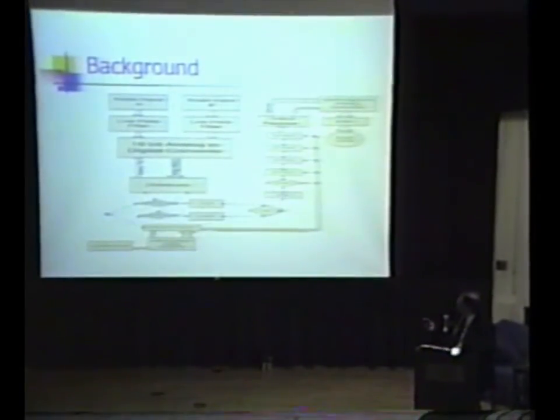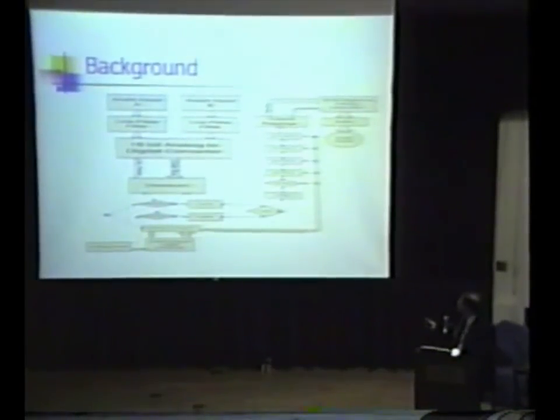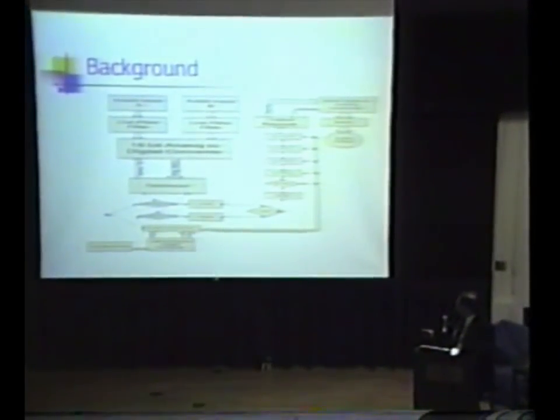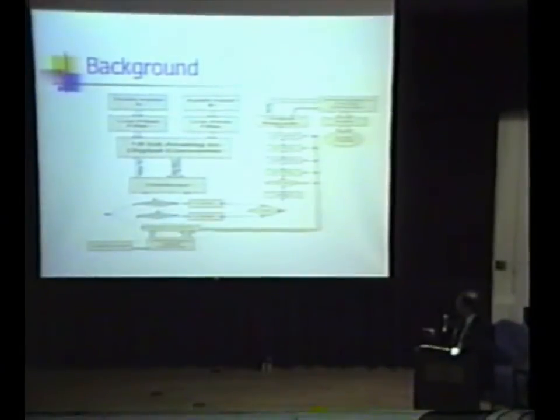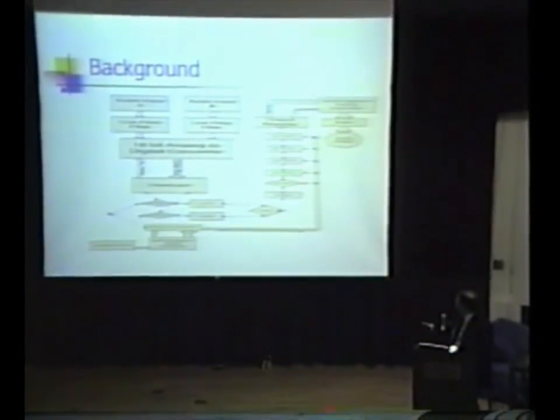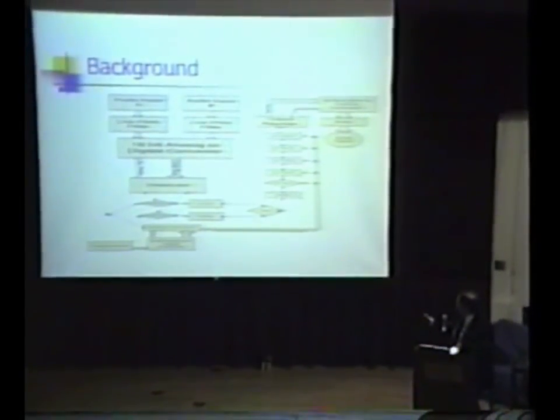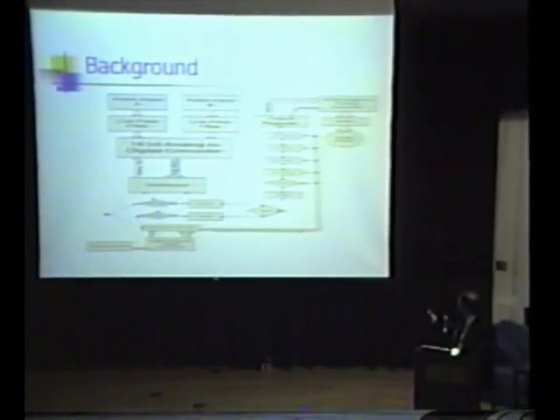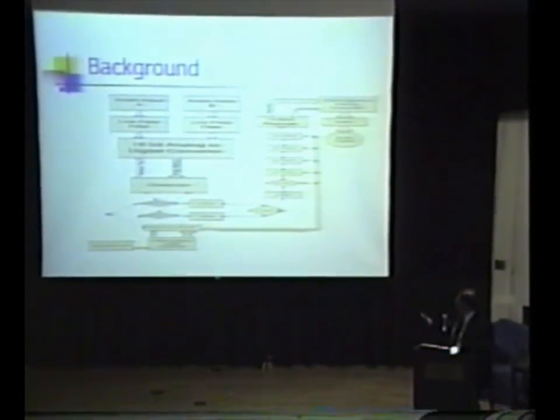On the block diagram, you can see the audio inputs going in, some analog filters. There's a capture of the channels and the capture of the potentiometer values to be used as gains. This right here is the mixing process, filter stages, and then finally through a D to A back to the audio output.